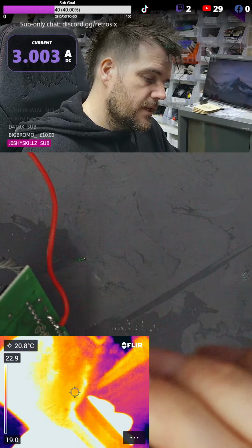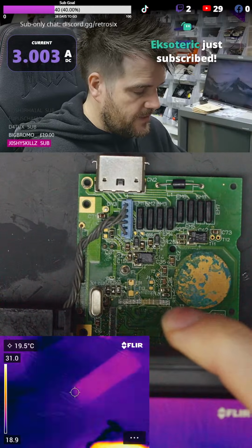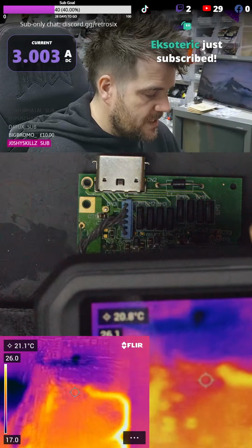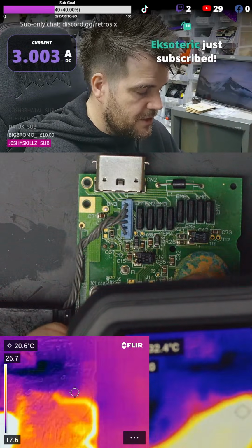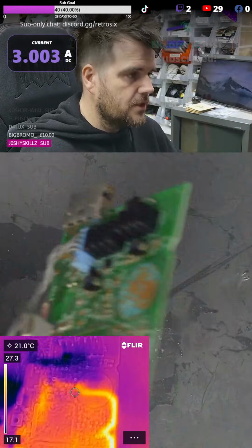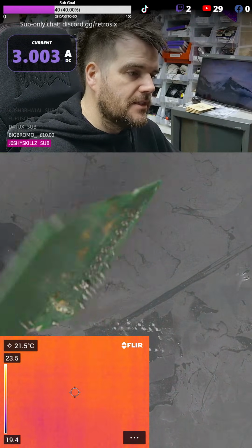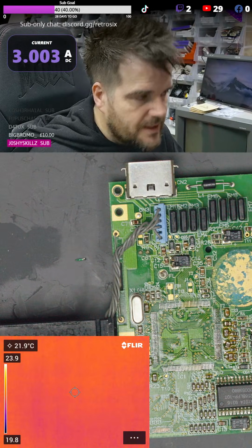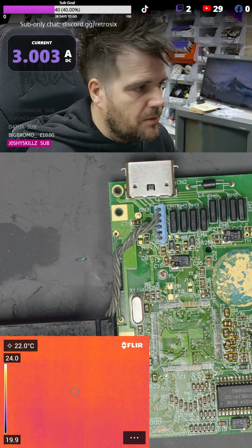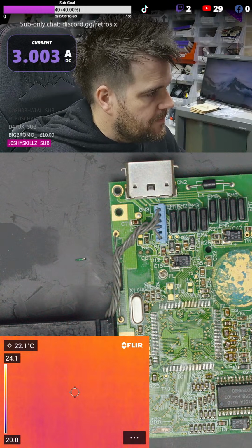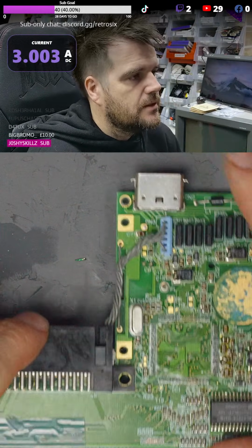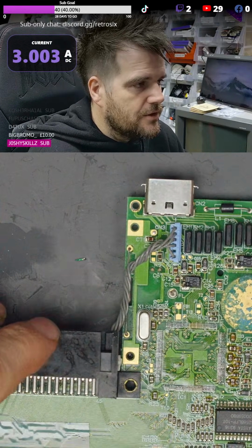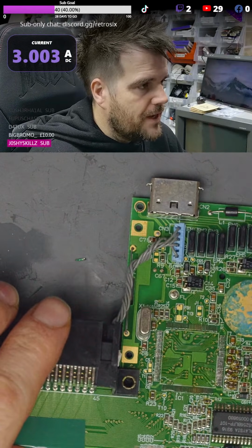So you're not going to see anything really, except the trace getting you somewhere in the vicinity. And you can suspect the short is up here. That's as close as you can now get. The rest is then really by eye. There's no other way of narrowing down that short. That is the biggest problem with actual dead shorts as they are. They're very hard. So they're kind of the worst ones to find.